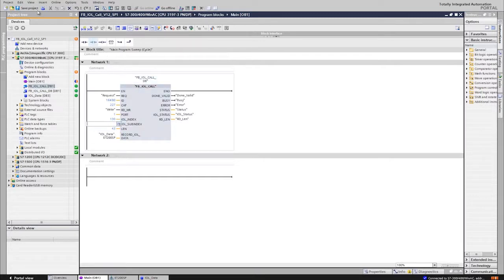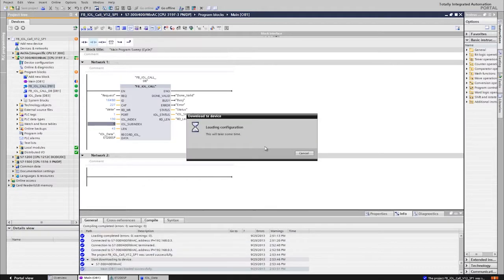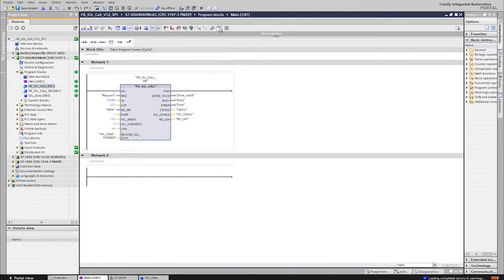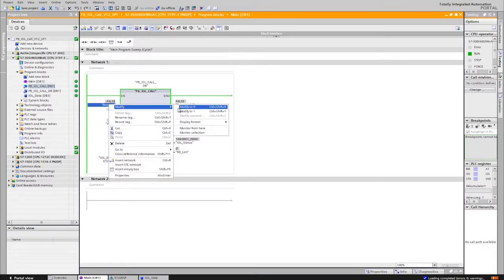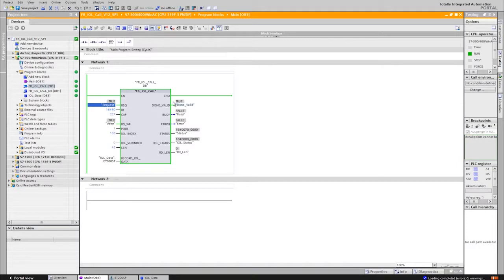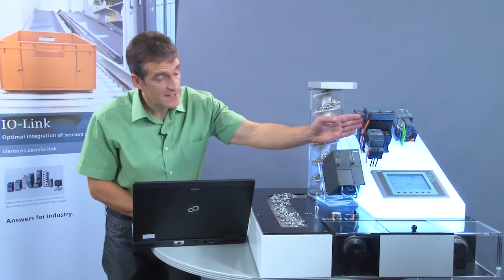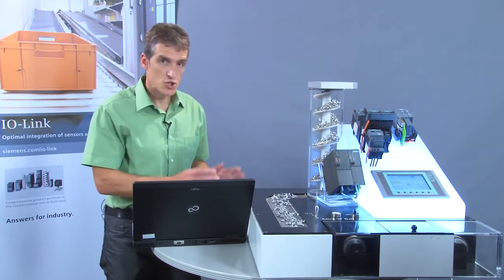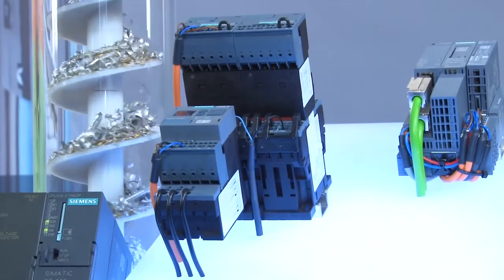The IO-Link parameters are now written to the new function module. I save the project and the parameters are then loaded into the function module. I select the monitoring on-off function. At the end, you will recognize, based on the done valid output parameter, that the transmission was successful. The replaced 3RA27 function module is now configured and parameterized, and the chip conveyor is operational. When the blocking current is reached, the chip conveyor shuts off immediately.